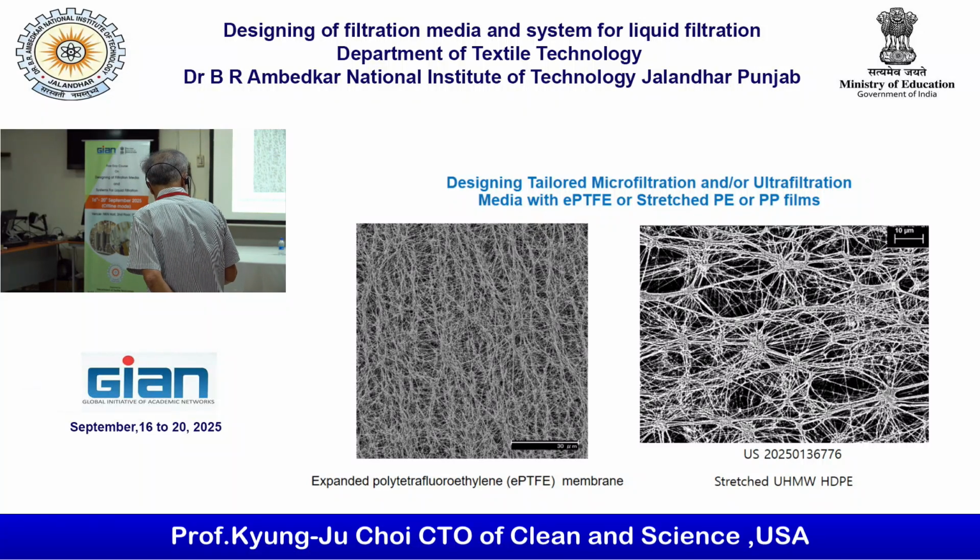I don't know whether you notice or not. This is the best material so far. Compared with the ePTFE, it still has lots of issues. There are a lot of voids there. Even though it's 10 micron, almost the same size, at the same magnification, the ultra high density polyethylene is still far below.